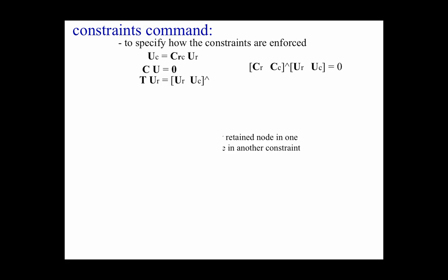Those constraints are important because these affect how the multi-point constraints are actually handled in the matrix equation. If you go to a textbook, there are many ways to write that matrix equation for the multi-point constraints, basically how two nodes are going to move together. I've put all the different ways here; these are all the same matrix equation, just expressed a little differently.